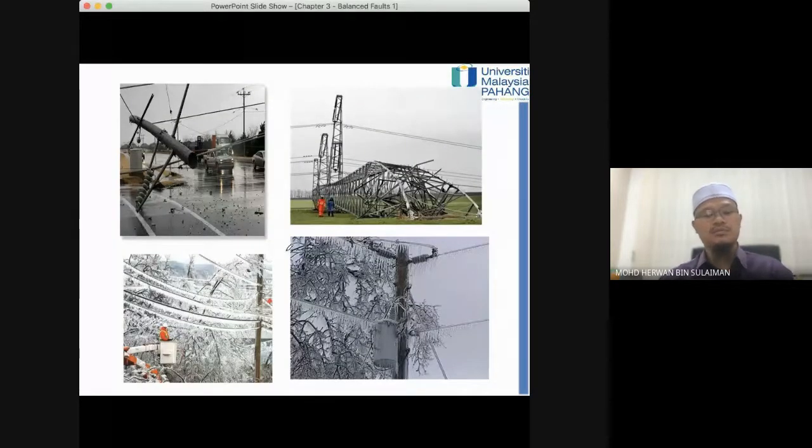When this happens, a fault is triggered, and normally in this situation we have relays and one component we call a recloser, right? Do you know what a recloser is? When a fault occurs, the recloser trips open, and after a certain amount of time, about 5 minutes, it assumes the system is okay and closes back. That means no contractor or maintenance needs to come and check. But if the fault is still not cleared, it opens again, meaning it still wants to make sure the component is clear.